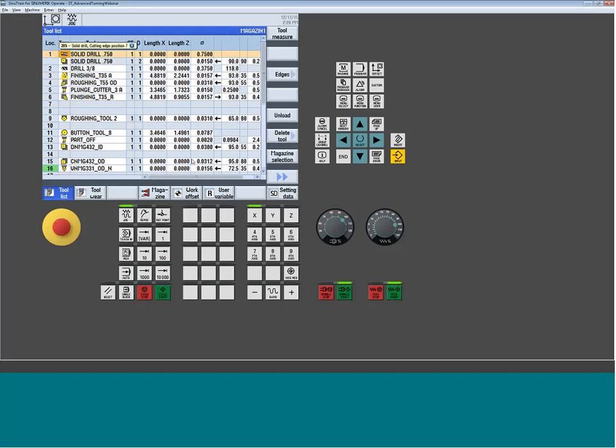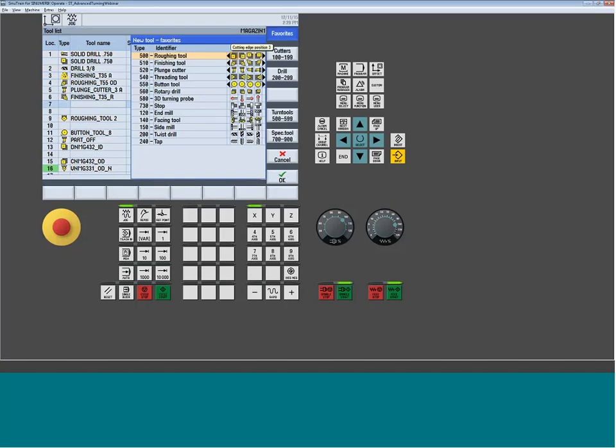So I chose first the solid drill field because it doesn't make me put a tip angle in. I certainly could have used our traditional twist drill, which a lot of guys are probably already used to, but it asked me for the tip angle. And then I would have had to obviously fool the numbers to make it come out flat. So in this case, when you start to create new tools, start to explore some of these other buttons. We always concentrate on this favorites tab, but there's all kinds of additional tools if I drill down. When I go to drilling, there is a tool called solid drill. Now, if I want to use a twist drill, it's okay. You can change it so it thinks that the front of it is flat. This one just keeps me from having to do it.